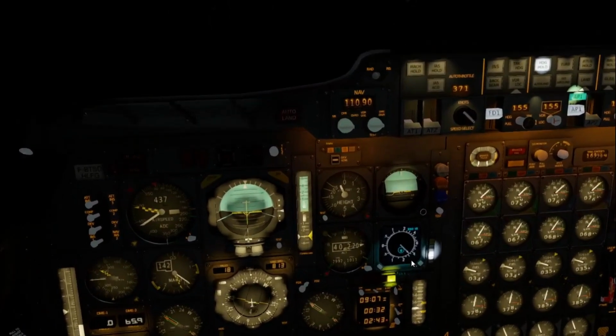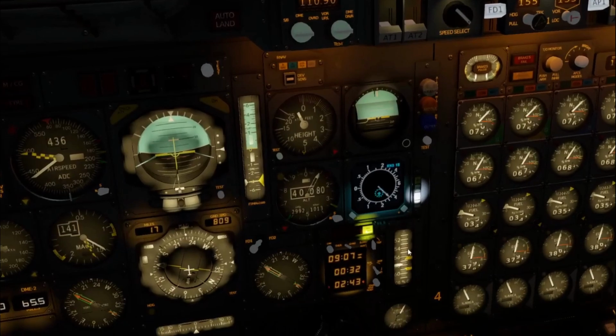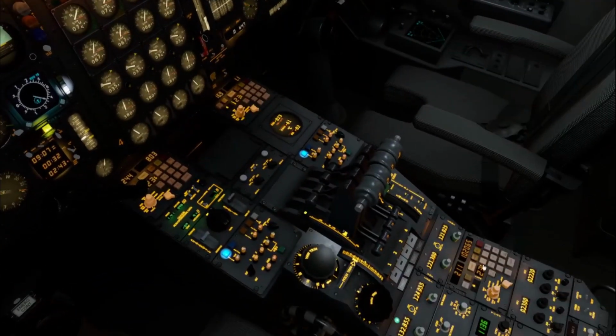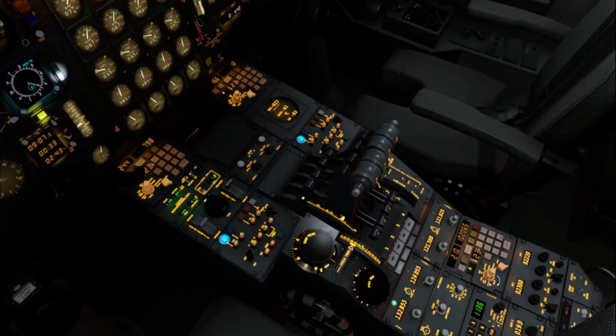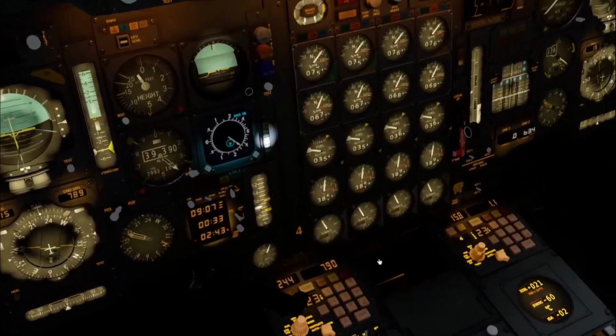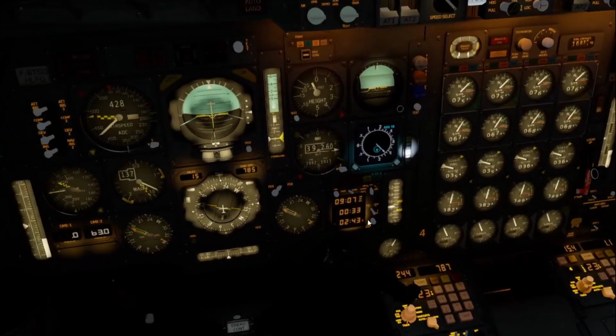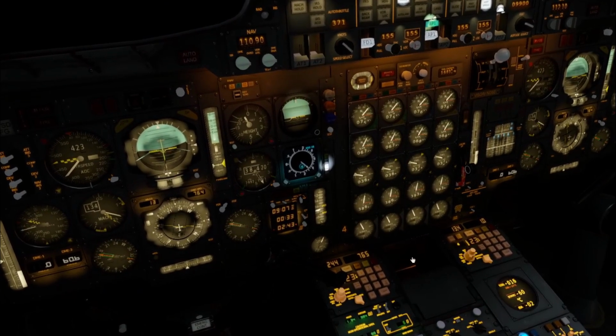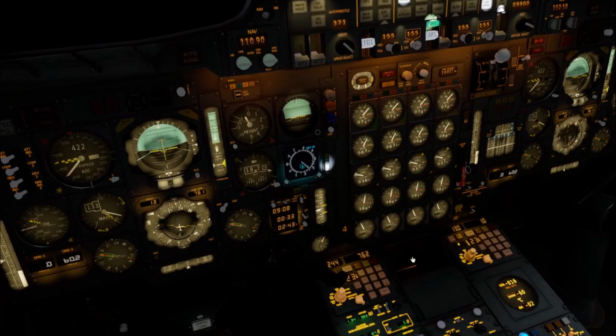We still have this comparator error. That means some of the INS units are not currently providing the same information. If there is a comparator error, that means this is an internal fault, or the units do not have the same values provided.